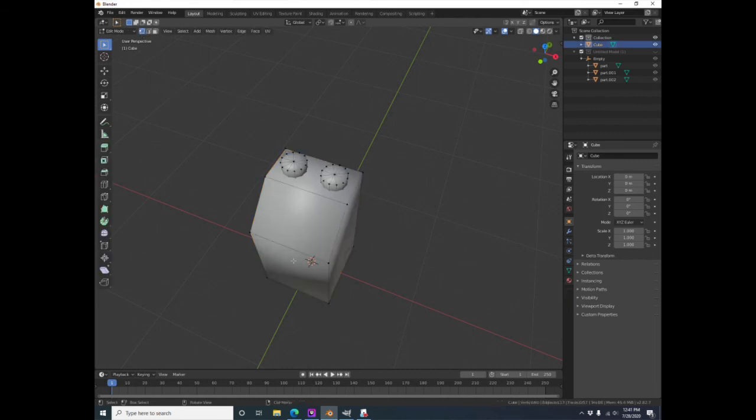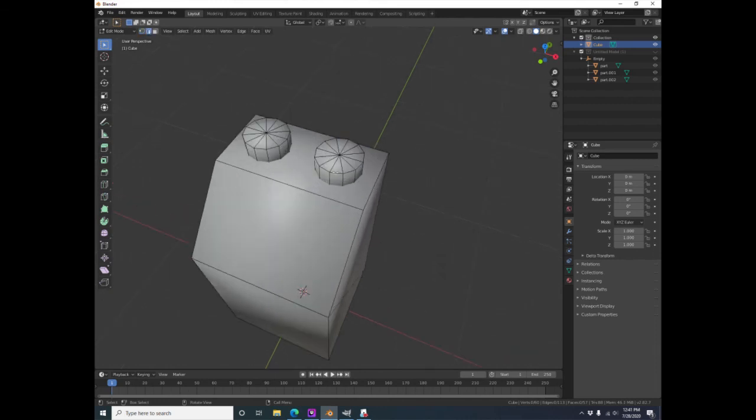And let's change our selection filter from vertices to edges. We're going to select all the edges that should define sharp corners. And we're going to leave out all the edges that either are part of flat faces or should be smoothed out, like the edges of the cylinder.